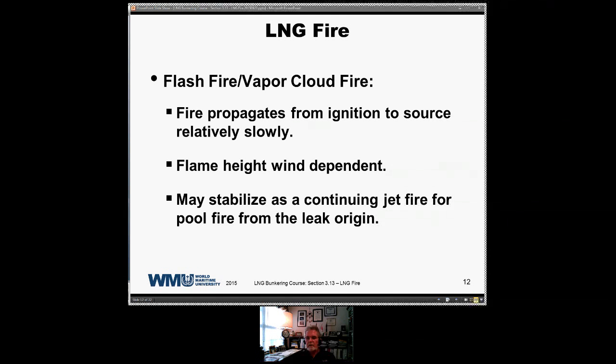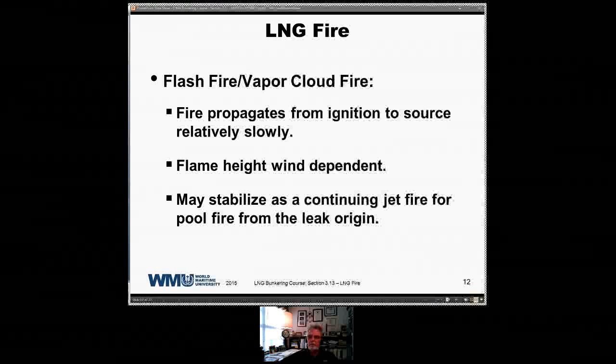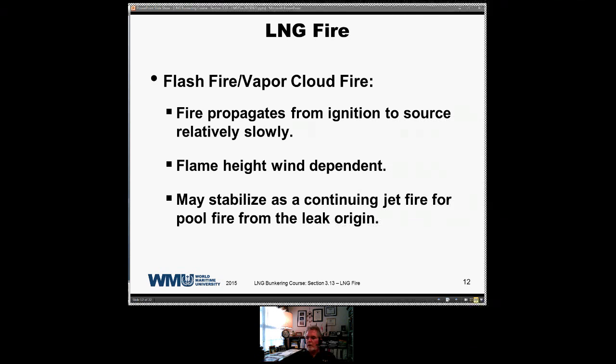the pipe under pressure, and then you have what's called a jet fire. That's basically fire under pressure, and the firefighting technique is a little bit different than that of a pool fire. It's one of those scenarios that, in all probability, if you can't secure the source of the leak, you will allow to burn under controlled conditions if at all possible.